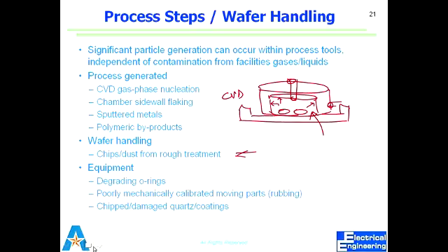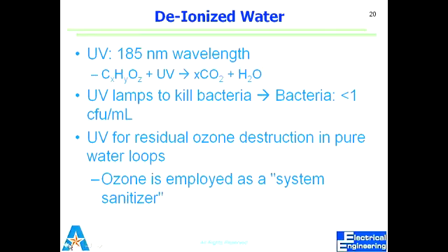I didn't want to give that right now, but I'll do it. So it's very important, always remember that. You'll see a lot of it. BHF, buffered hydrofluoric acid. It's also called buffered oxide etch. It's used from, I think, 6 to 1 to 10 to 1 ratio of DI water to acid. So we dilute the acid. Of course, when you dilute, 6 times would be water in there.